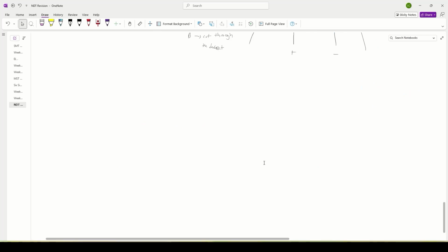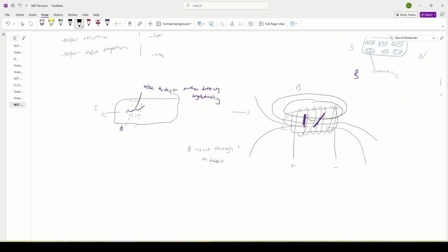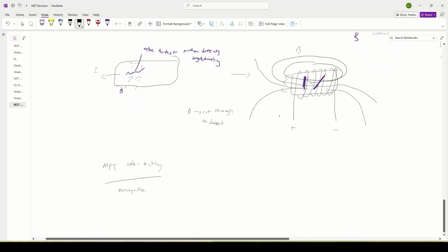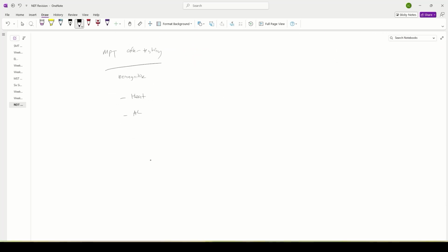Then you have to demagnetize after you test for defects. Similar to how we clean the defects from the liquid penetrant, we also have to clean from the magnetic material. To demagnetize, for example, you can use heat, alternating current, or even vibrational demagnetization: mechanical plus magnetic field. Demagnetize, for example, with heat above the Curie temperature, at which it loses its magnetic property, or alternating current demagnetization, degauss.